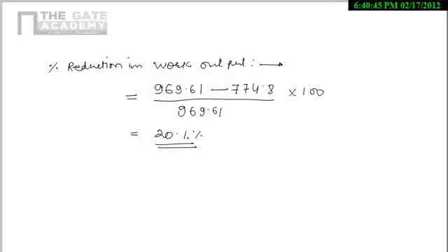Now we have the enthalpy at all points, but for heat addition in the actual process we are interested in H4. H4 I can calculate as 173.88 plus 2.51, so it comes to 176.39 kilojoule per kg.